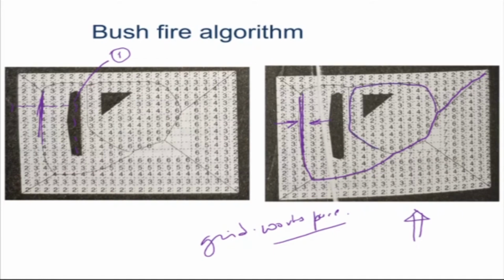But a computer would find this very easy to compute and do, because this is in a grid form and these are numbers. So you can write an algorithm very quickly to do this and find the deformation retract. Okay. Now if you are here, say I have initial point, you simply can connect to the node, and suppose you want to go here, this is my goal point, so you can simply follow this path like this and go there. Okay. So this is basically called the Bushfire algorithm.